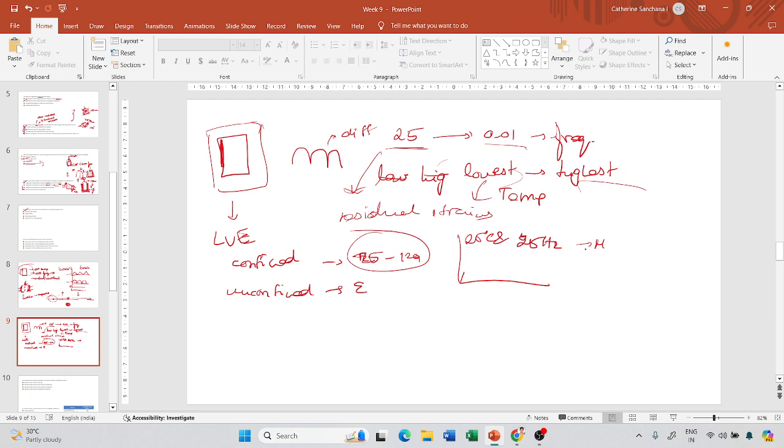We call it a seed modulus because the equipment knows that you require a strain of 75 to 120 or 125 micron. Using this modulus, it will find out what stress has to be applied on the sample. So it will apply that stress to the sample, and it will apply 5 cycles.